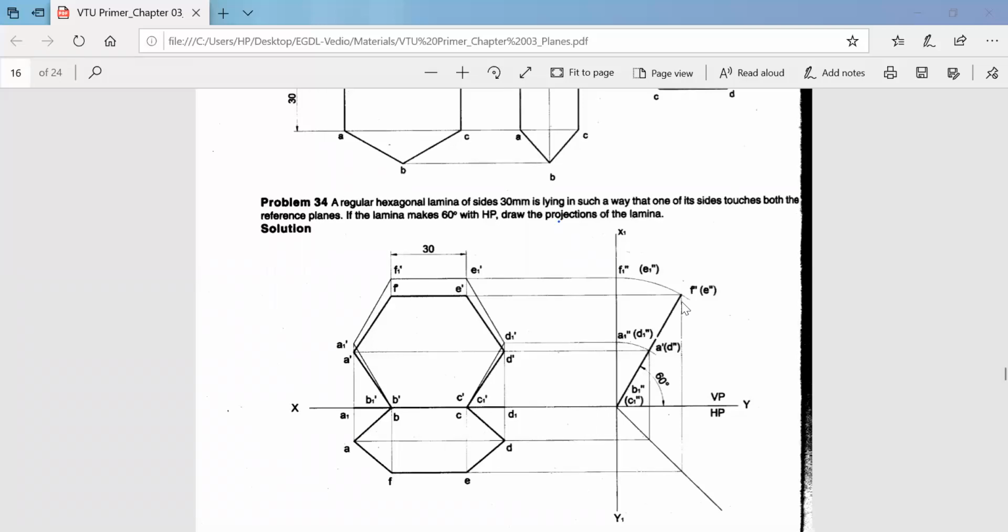After doing the naming, what is our ultimate goal? We have to show one more side in the horizontal plane also. For that you need the projection down. How can you extend the projection of the side view to our top view? The only option is to take a 45-degree line. You will take a 45-degree line and take the projection down from both the points. After taking the projection down, you will extend the projection here to the back side, 1 and 2.